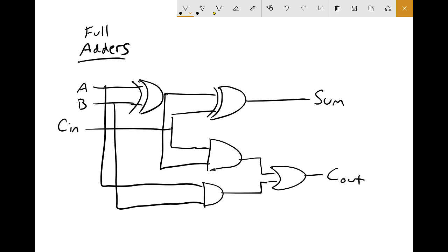This is what the full adder circuit looks like. Let's try to break this down a little bit, because it does look a little bit convoluted if you're just taking a glance at it. We saw in the half adder that our inputs, A and B, go into an exclusive OR gate first, and return a sum. But this time we have another input, called the carry in. So, because we're putting two half adders together, we're going to pass these inputs into another exclusive OR gate. These inputs are the product of A XOR B and the carry in. This will finally give us our sum.